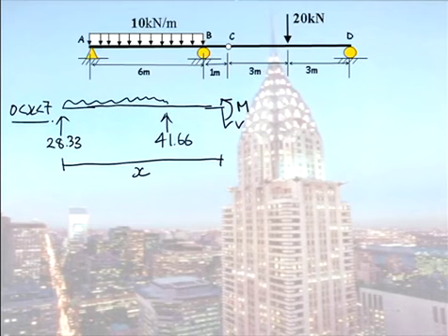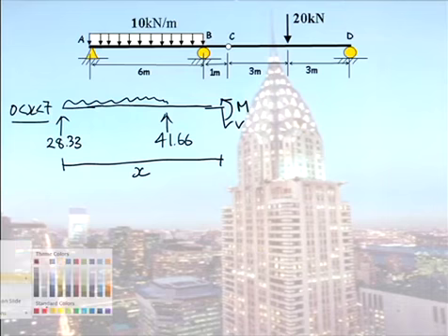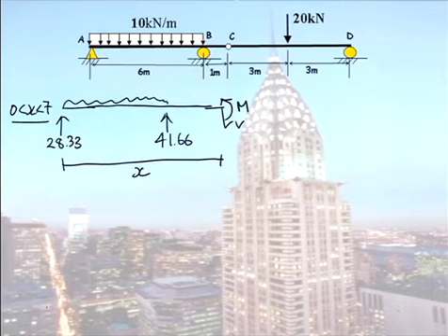So the first thing we look at when we look at this problem now is to say, I have a discontinuous uniformly distributed load. That means it doesn't run into the cut. So when you make the cut, you have to consider it to be as far right as possible. So you would make sure you encounter all your loads. So because it doesn't run into the cut, we are going to assume it does run into the cut. And because we can't go adding load, we will then be taking the same load away from the bottom. So why are we doing it? We are doing this so we get one equation that is valid for the entire beam.